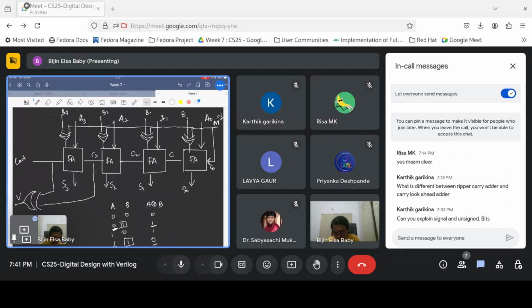And this XOR gate finally is to find out the overflow, which I explained in the previous slide, that is 0, 1 or 1, 0. So this XOR gate at the final stage is for checking the overflow. And when n equals 1, it will do the subtraction, and when n equals 0, it will do the addition. So this is the circuit for the overflow of signed numbers.